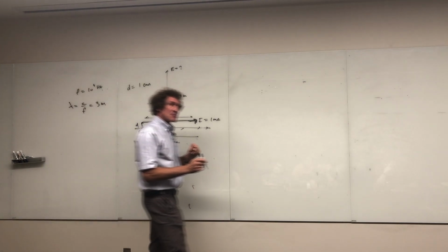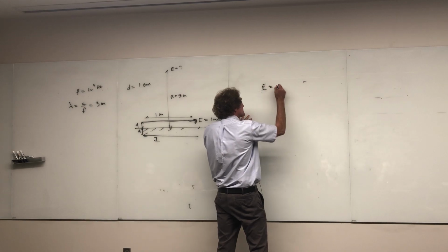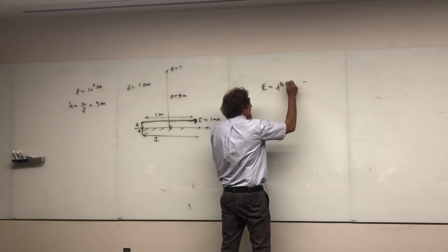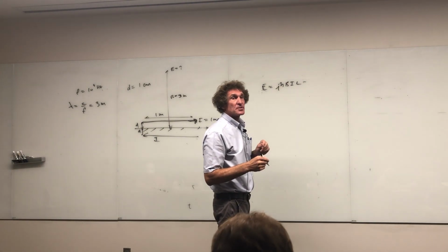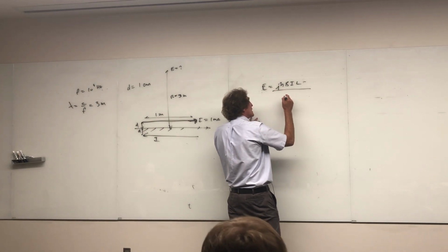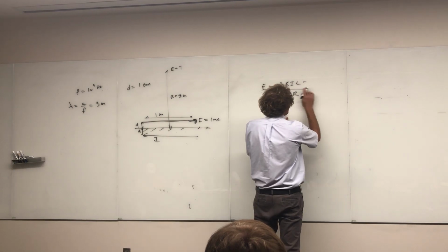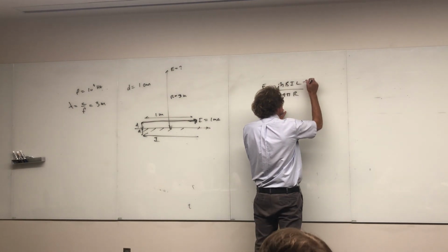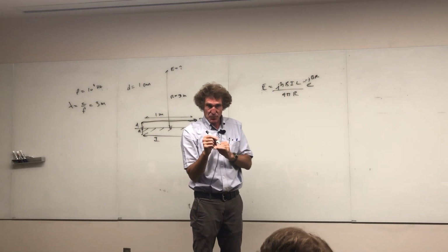In general, the electric field from a short dipole, the general equation is j eta beta I times L. So it's the magnitude of the current proportional to the length of the antenna as well. Then it's divided by 4 pi r. That's the radial distance. Then there's the function e to the minus j beta r. That's a phase function that becomes very important in this problem.